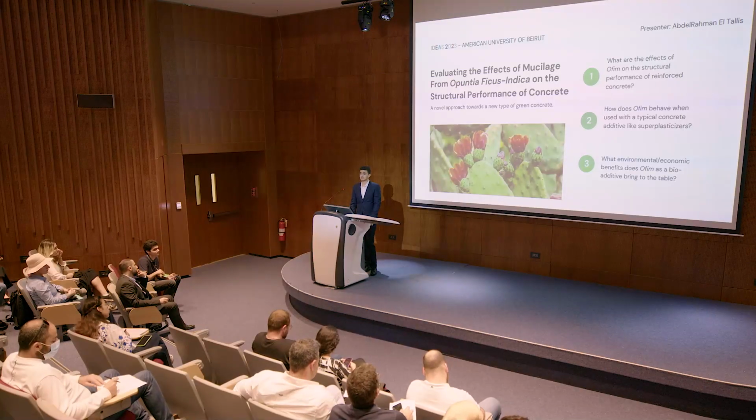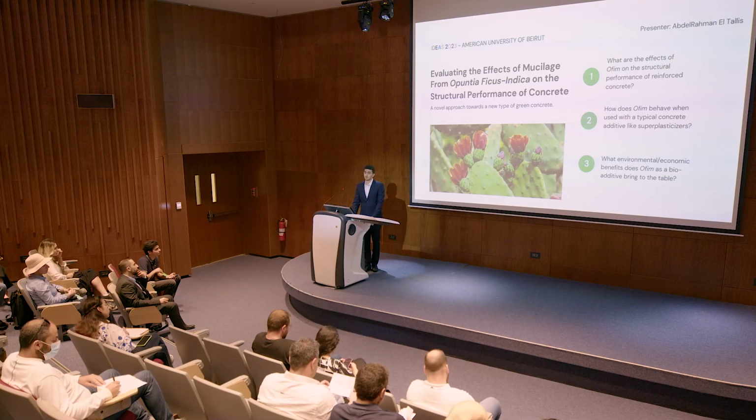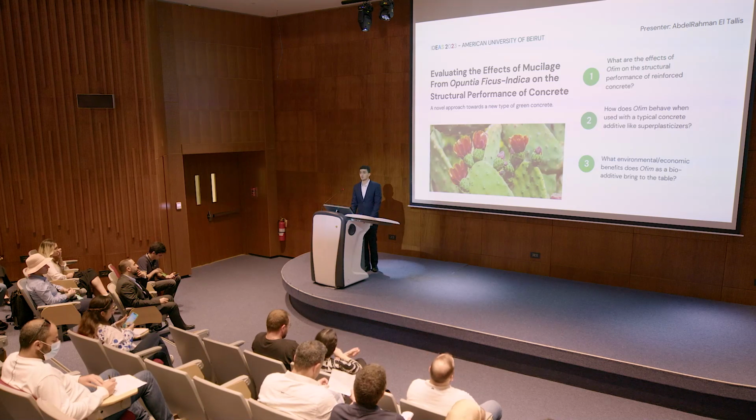We exhibited improvements in every single one of them, with the most significant being related to the shear properties. In short, OFM-modified concrete was able to withstand higher loads and became significantly more ductile. We also reported good behavior with the superplasticizer, as well as better bond with the embedded steel reinforcements. This was attributed to the adequate bonding between the mucilage and the cement.